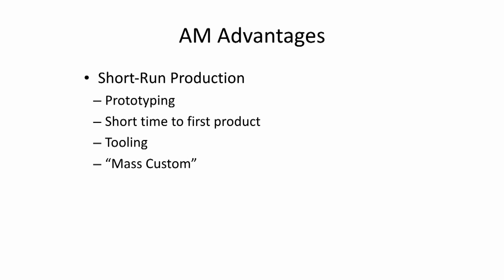Additive manufacturing frequently more effectively makes one part at a time. One of the most important advantages that additive manufacturing has is its ability to change the supply chain. It's not that it is superior to other methods of production, but rather that it can fill niches that the others can't. So even just a couple $100 3D printer, like the one we have here on the table, can produce very complex parts with very little in terms of requirements for tooling or technician skill, then this changes the way in which we can distribute production and material and finished products separately from each other.